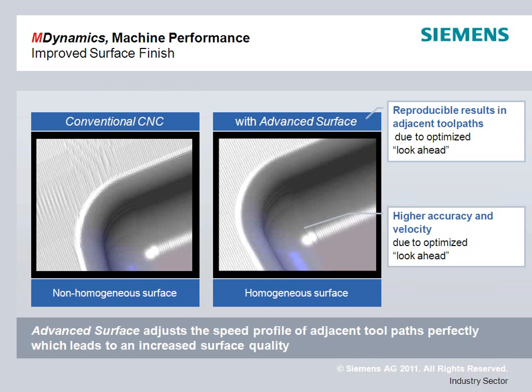This is another sample part that we also use internally. With the new Advanced Surface functions, we've taken some of the marks out of the part as we transition from a flat surface down through a corner. Again, the easy thing for you is that with Advanced Surface, there's nothing that you need to configure to make this work. You just need to make the Cycle 832 call.